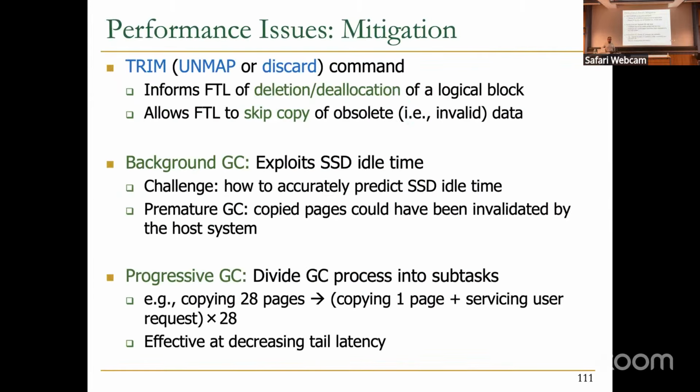And that's why, in the past, when we were profiling the performance of SSDs, we had, for example, very good performance, and at some point it was super clear that garbage collection kicked in, and now the performance was just so low. But now it's not that dramatic. So you can see that the performance is okay, and then when we have GC, we have a lower performance, but it's not so dramatic that, for example, the user may not actually feel it anymore.